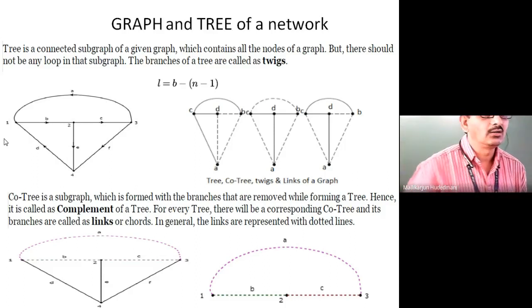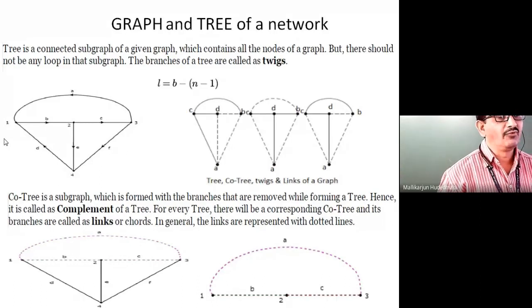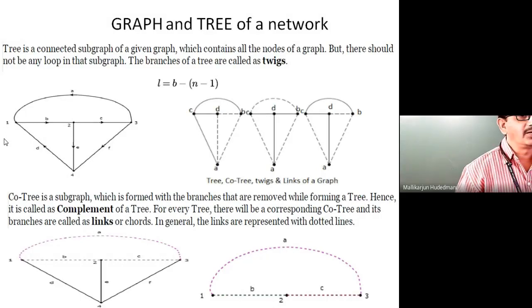So you just look at the bottom representation where I have the same diagram with the upper 3 elements, element B, element C and element A, put dotted. When I put it dotted, you will find element 1 to 4 solid, element 2 to 4 solid, element 3 to 4 solid. I mean there are 3 elements from the 4th bus touching outward, and the remaining 3 elements connected 1 to 2, 2 to 3, 3 to 1 were put dotted. Of course, there is no closed path visible because there is no solid line connecting each other or closed path traceable to you. Then that is called one of the possible trees for your requirement.